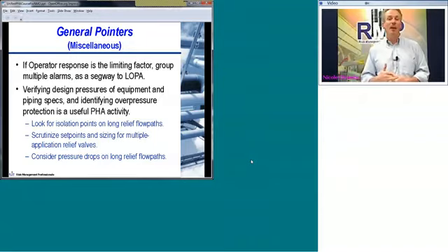And also, multiple alarms can be good if they're contributory towards diagnosing the event and not clouding the issue. It can be bad if they're not properly prioritized and there are so many different things going on that the operator has trouble diagnosing what's happening and taking corrective action. So any way you slice it, it's a single operator action, and that segues into LOPA because they only give you 1 credit for operator response using 1 or multiple alarms.